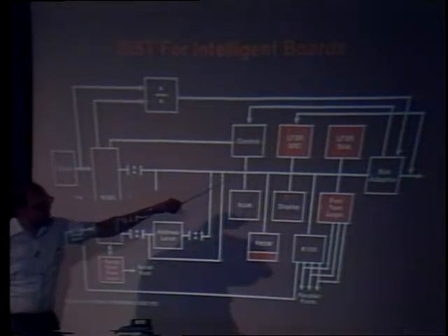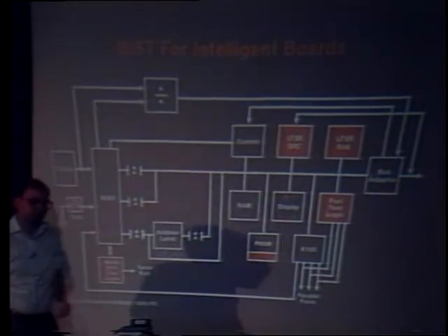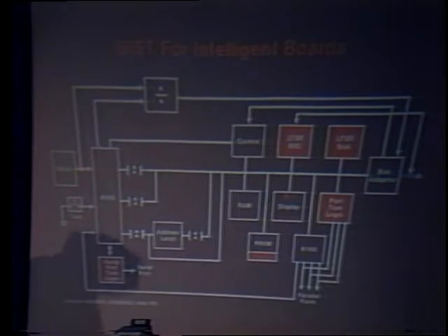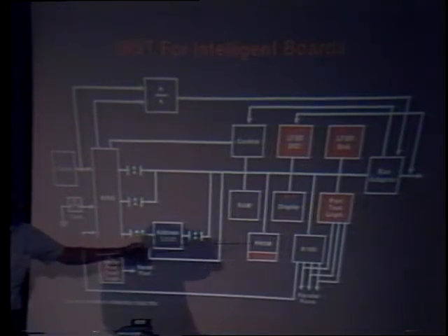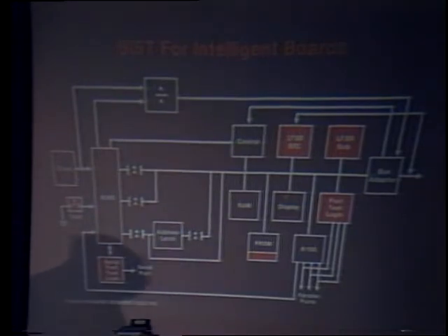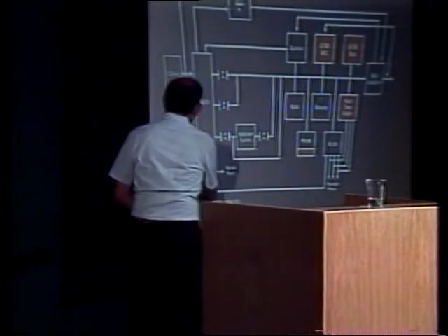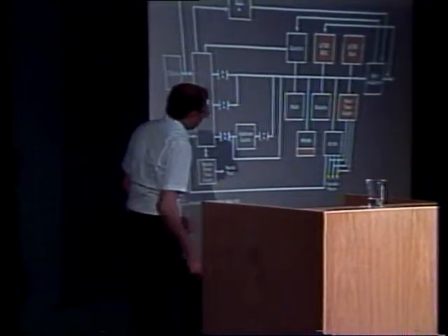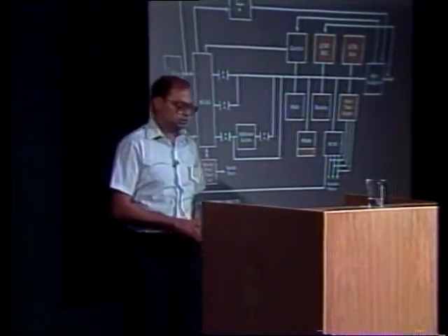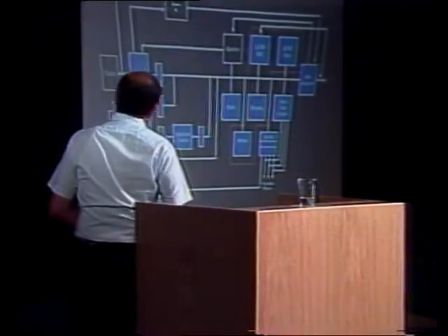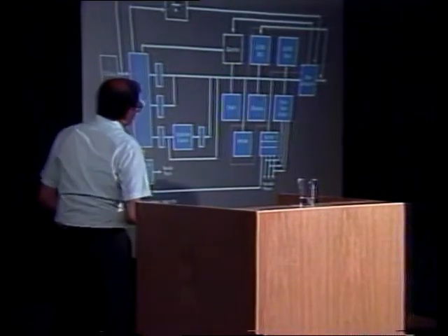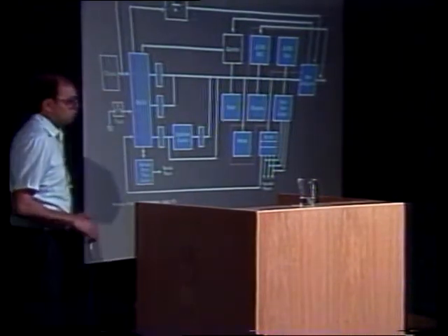One to provide the test vectors, other to capture the responses. And by doing so, plus in addition, they had some test code sitting in this PROM. And these are, by the way, loopback features: serial port loopback, and that one is the parallel port loopback. So with the help of those 2 linear feedback shift registers, they claim that they were able to self-test this entire board.